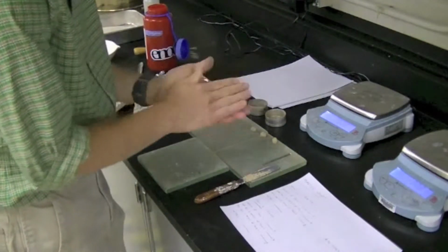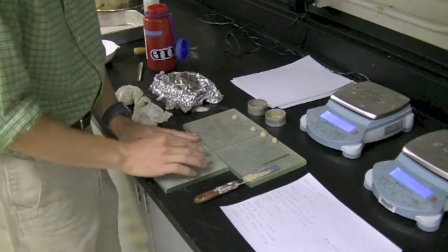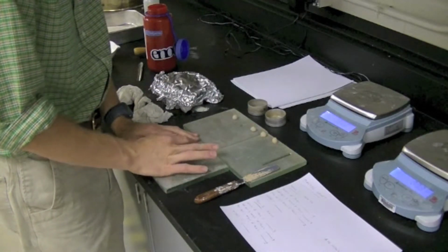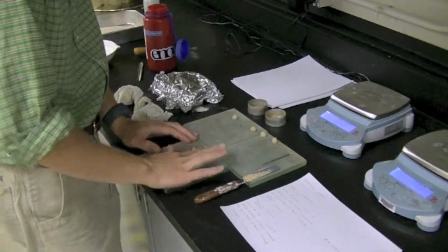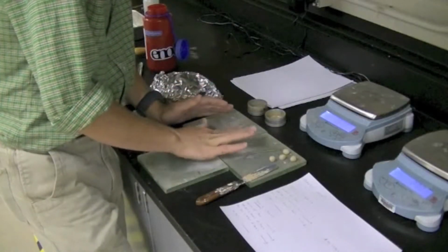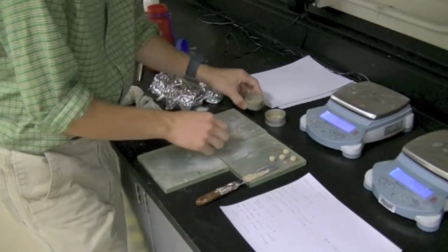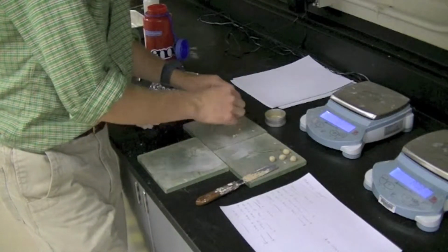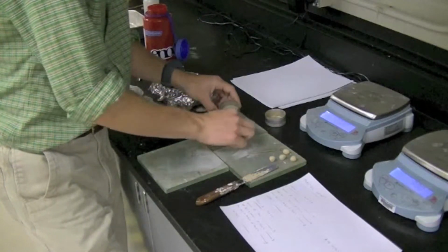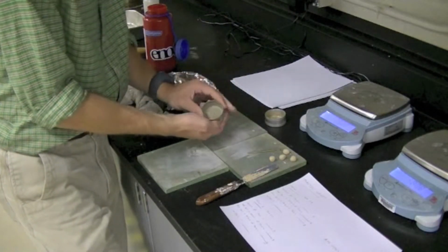Next, begin to roll the balls into 1/8 of an inch threads against a glass ground plate. Allow the soil to break up so that it becomes between its semi-solid and its plastic state. If the soil thread does not break apart or crumble, re-roll the ball and continue rolling until this occurs. If need be, re-roll the same thread multiple times.